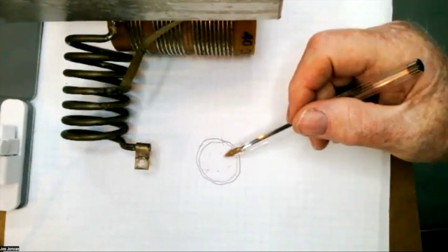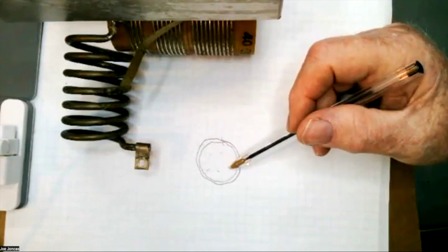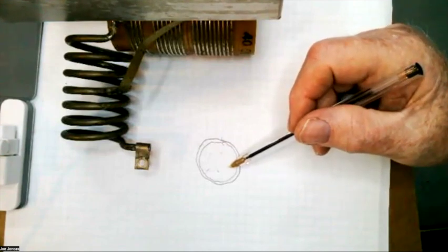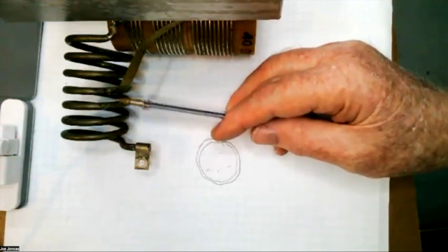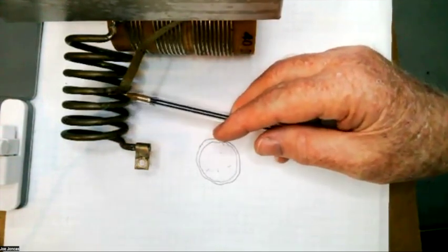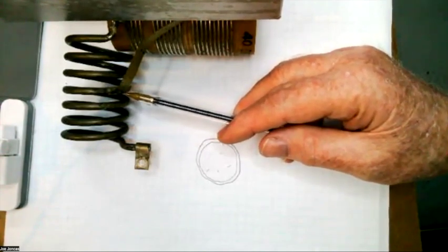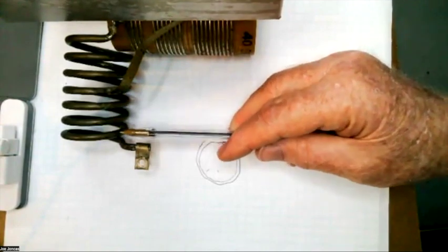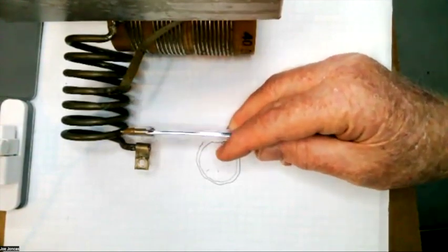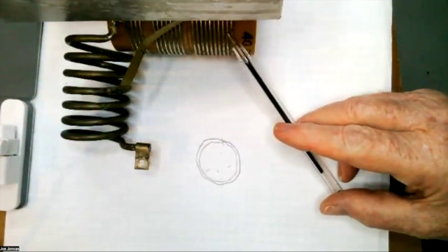60 cycle AC does not have much skin effect. 3 megahertz has quite a bit. 100 megahertz has a lot more. This part of this coil here is supposed to work at 30 megahertz. So does that affect the heat that's being produced as well? Yes, because of the resistance, if you were just using these little tiny wires here,